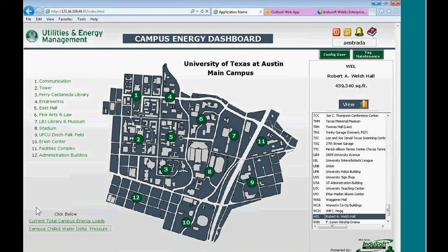We have a GE Prophecy historian that we'll be pulling data out of. We're doing this already, but we're able to offer the operators of the power plant and other engineers the ability to trend data over the web through IWS or through a secure viewer.